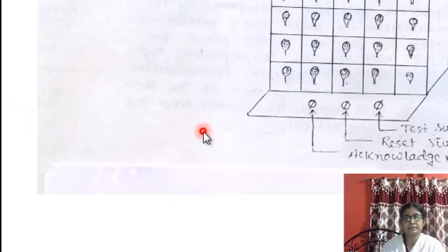Annunciator. In the last class we covered the transmitter, which is the device for signal transmission from a process to the controller, and the control action signal generated from the controller to the process. And the annunciator is another unit in a process control loop, which is used to produce an audio-visual alarm signal in the central control room in the process plant.